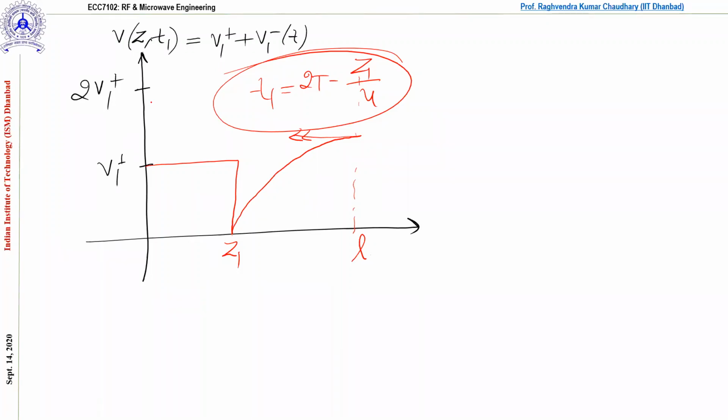Based on that, we can guess whether it is capacitive or inductive, and this is really very helpful, because somewhere at, let's say, 2 or 3 kilometers, we may have a capacitive element or a mismatch. So one can say this is capacitive and this is inductive. TDR is actually one of the instruments where we use this concept. So this is all from my side. If you have any questions, please ask.